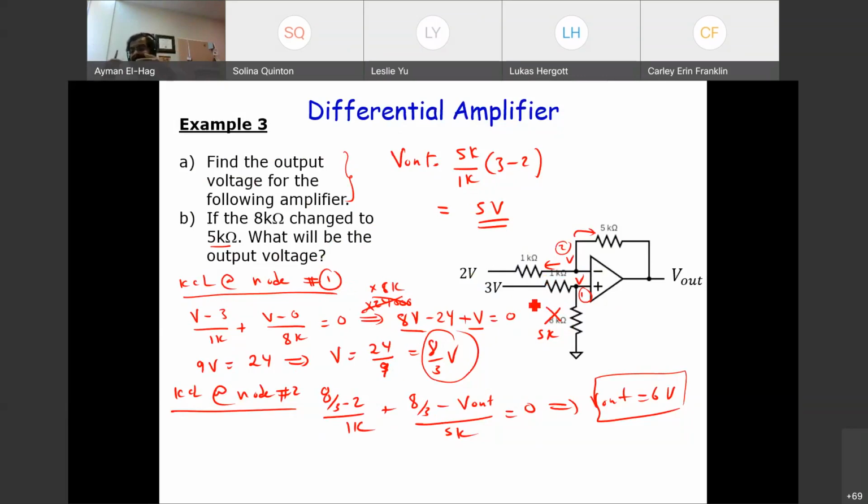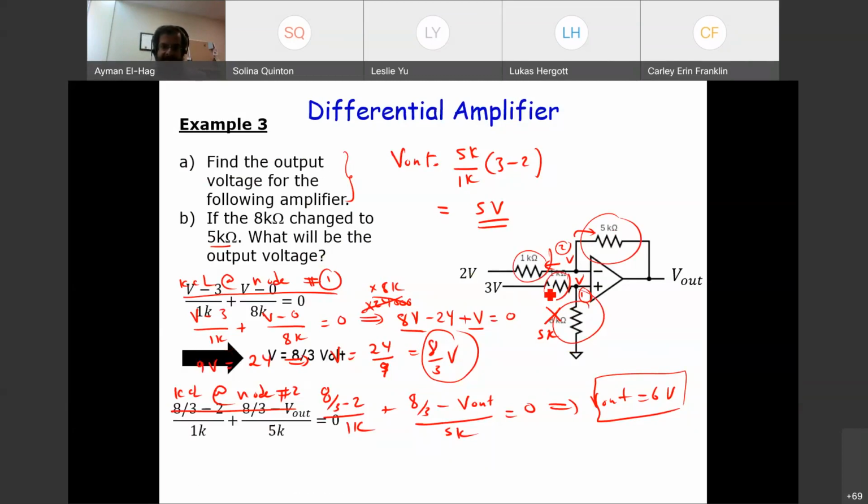But when you fabricate them inside the chip, you have a very good control on them. So this is why usually everything is fabricated inside one chip, so you don't see these resistors. They are internal, so you have no control over the gain. You will actually have a specific gain, and this is one of the disadvantages of the differential amplifier. But it's not only that. There is another severe disadvantage with the differential amplifier, and this is why we move now from the differential amplifier